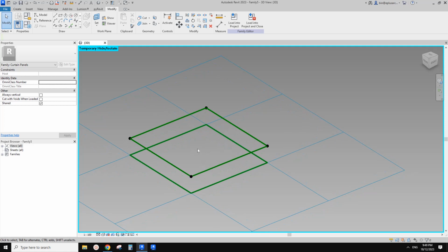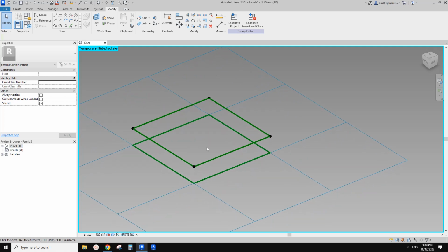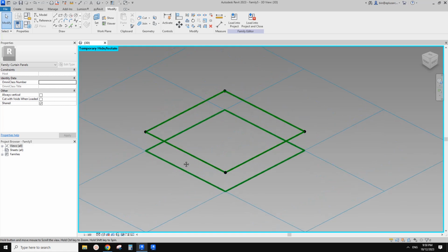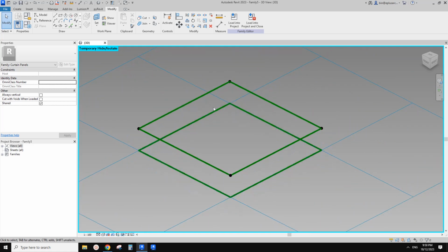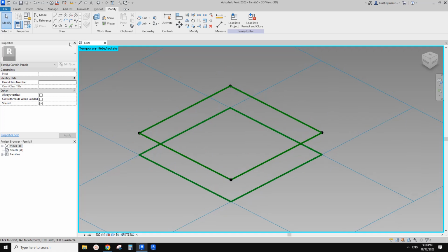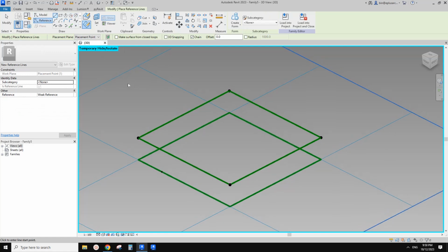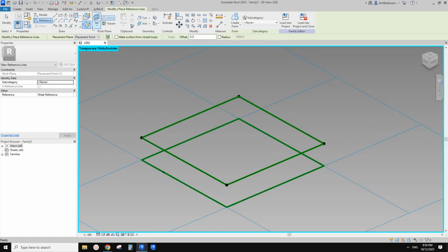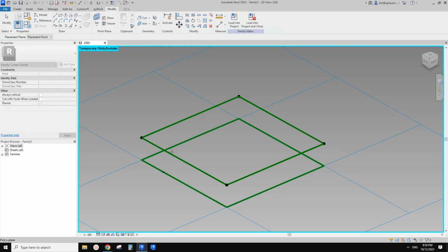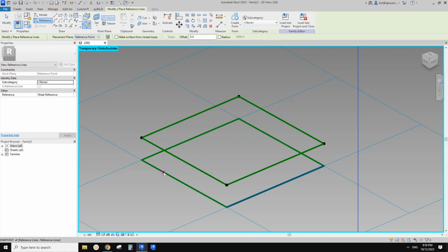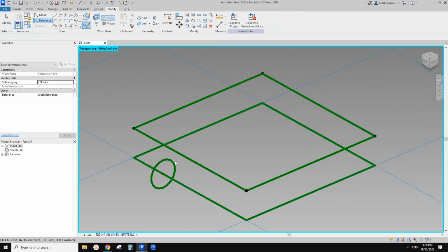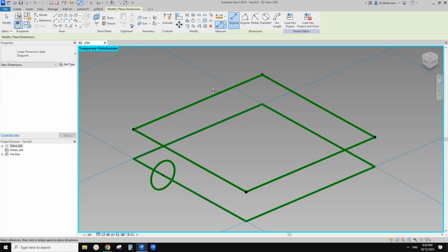Okay, so the next step, hang on, do we need these? Yes, we need them. Now we're going to create a frame on the bottom plane. Let's use a point, use draw on face, and place it on any of these reference lines. Just place it here, and then we can use reference line. For the profile, I'll just use a circle to make it easier. Use draw on work plane, set work plane, pick this work plane, and create a circle. Now we're going to create a diameter parameter. Let's dimension, go diameter and pick this.